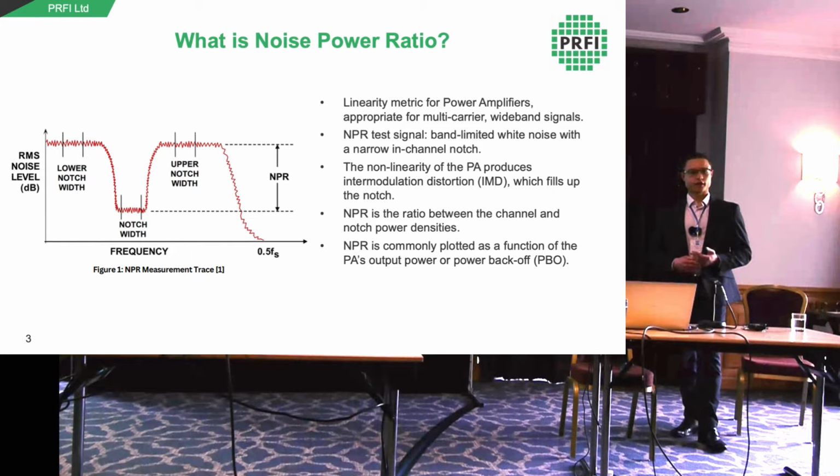When this is fed into an amplifier, the non-linearity of the PA produces intermodulation tones that then fill up that notch. The noise power ratio is the ratio between the channel power density and the power density inside the notch. This is commonly plotted as a function of the PA's output power or power backoff. Noise power ratio is a metric that's been around for quite a while, originally for, I think, FDM systems, but more recently it's used in defense and SATCOM applications.